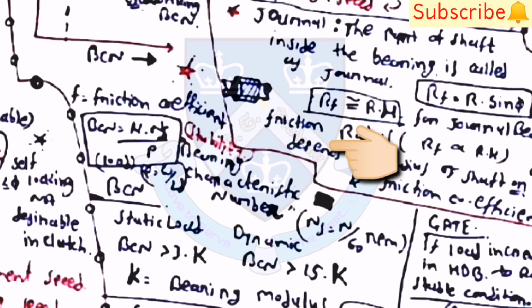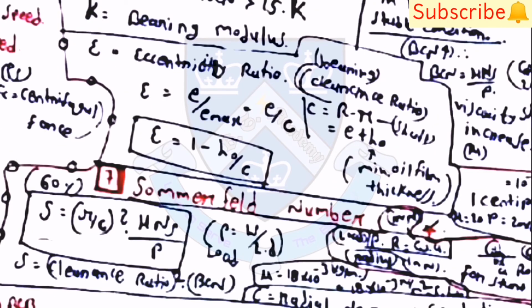Then for the journal bearing, RF is nearly equal to R into mu. Then RF is equal to R into sin alpha. Then the bearing characteristic curve: you can see that BCN is equal to mu into NS upon P. This is a very important equation. Then for static load, BCN is greater than 3 into K, and for dynamic load, BCN is greater than 15 into K. Then K is equal to bearing modulus, and epsilon is equal to eccentricity ratio.